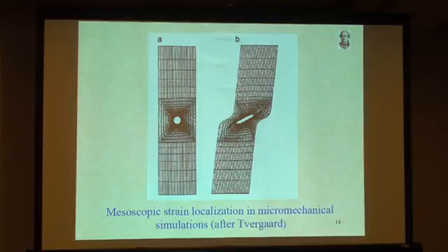So you see the initial cell shape, and because of the shear loading, you see that the strain concentrates within this thin region. This is in a periodic voided material, so you must imagine that there is another void here, and so on. So the strain essentially concentrates within a planar band, the thickness of which is of the order of the void radius or void diameter.